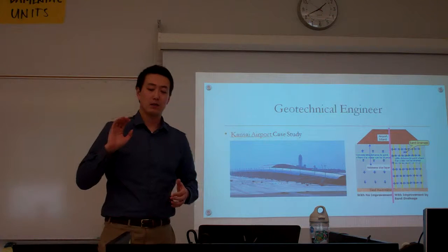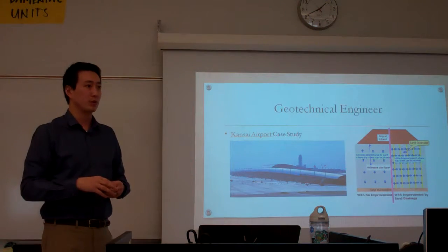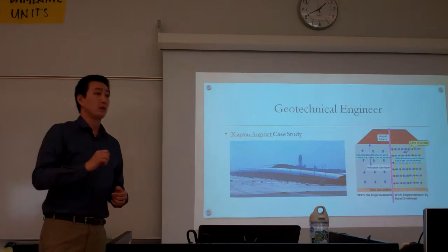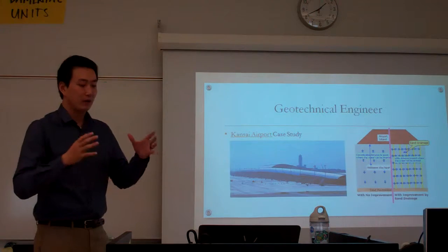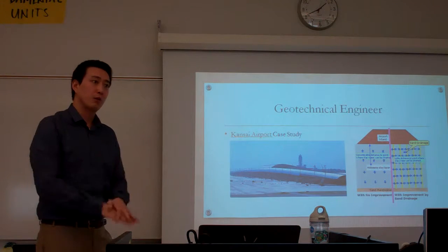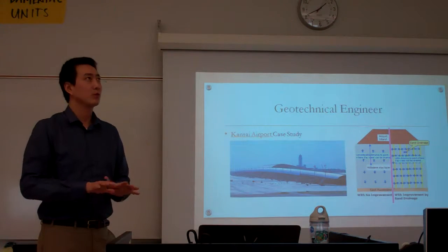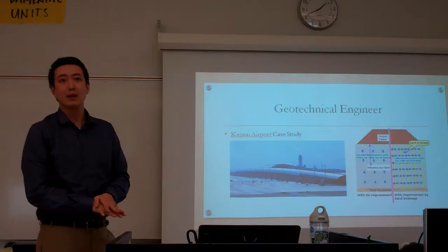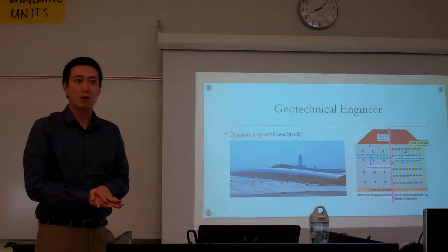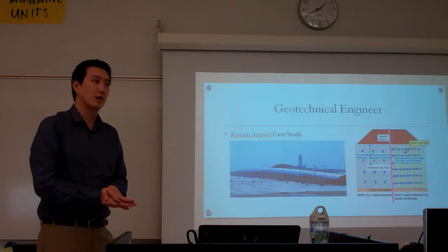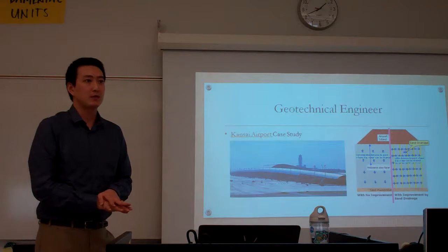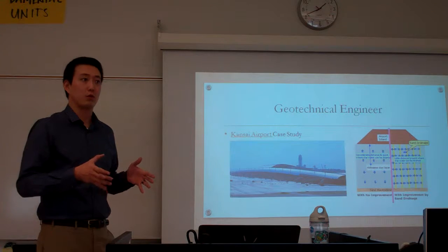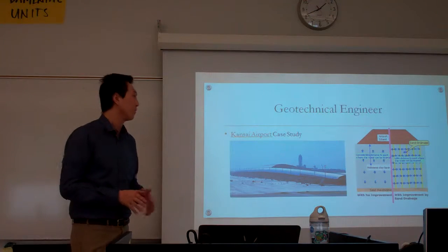If you ever take soil engineering or geotechnical engineering in college, clay retains a lot of water, whereas sand doesn't retain very much water. If you have a bucket of sand and pour water on it, you push down on the sand, the water is going to flow out. Whereas if it's clay, you push down on the clay, it's going to hold its form, and you think you're all good. Only a year, 5 years later, the water slowly seeps out, and all of a sudden the building you put on top starts to crumble because the soil that you put the building on starts to fall apart.